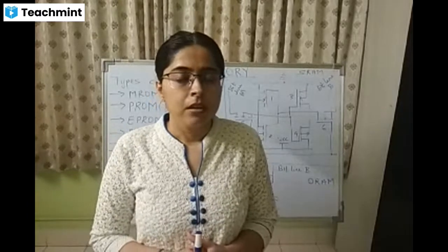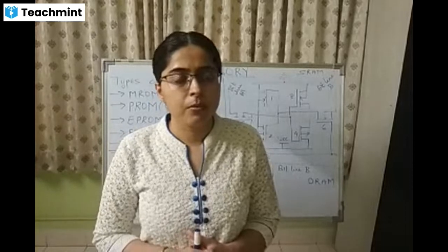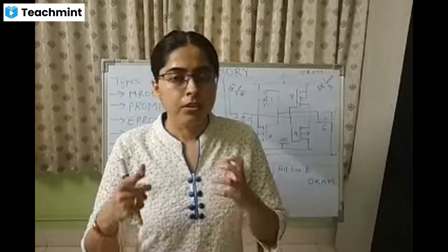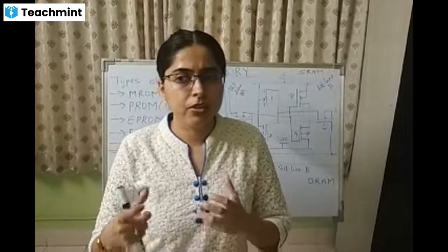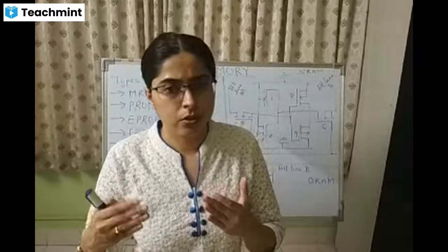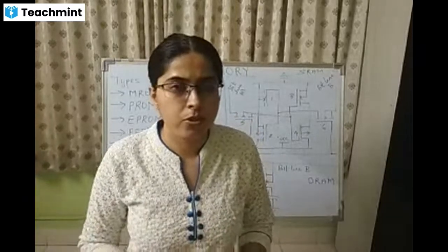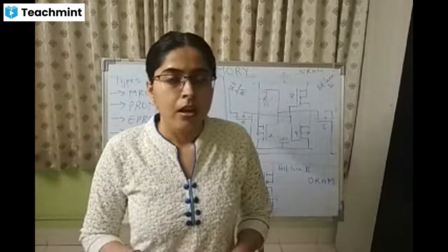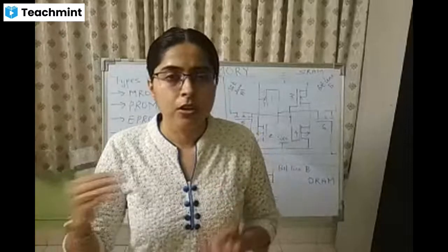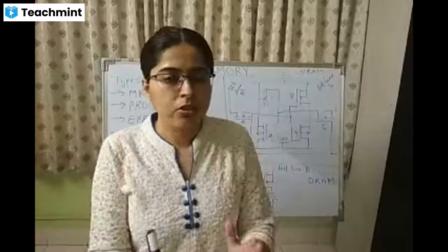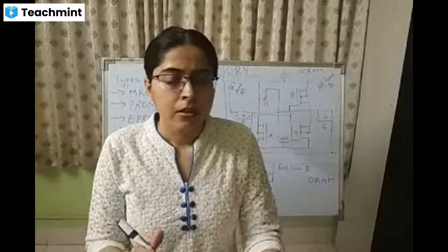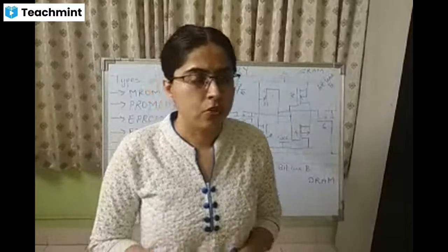And there are sectors or pages. Memory is divided into sectors or pages, and before reprogramming, it is very important that each sector or each page should be, I mean to say, cleared. Then after clearing each sector, by sector-by-sector clearing of each page, we can reprogram the chip. At one instant, all the sectors of memory are not erased. One by one, sector by sector, the memory is erased.